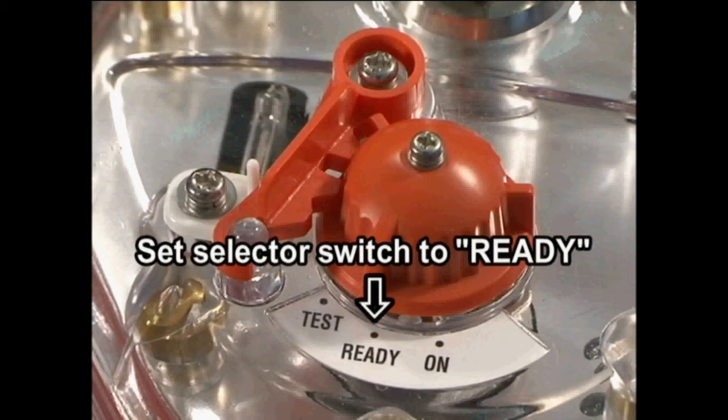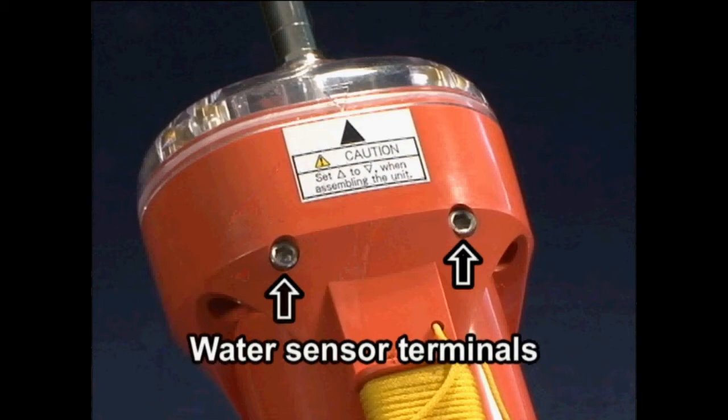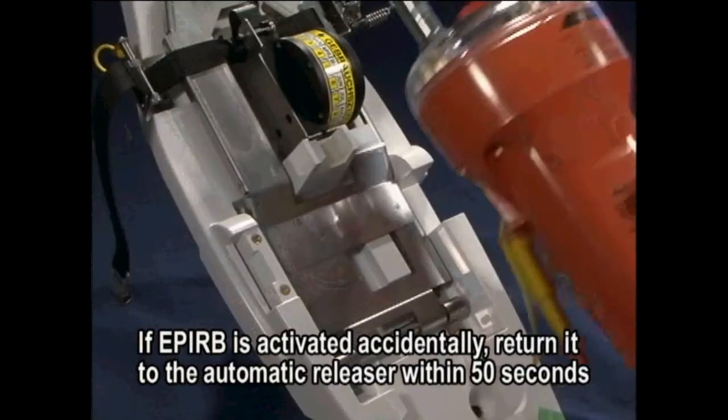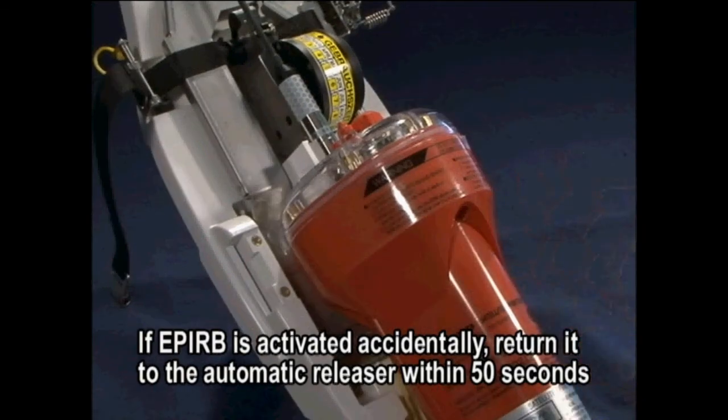When conducting maintenance, make sure that the selector switch on the main body is set to ready, and wipe the entire main body with a piece of soft cloth. Wipe each of the water sensor terminals separately. If the EPIRB is triggered by wiping of both water sensor terminals, you have 50 seconds in which to replace it in the automatic releasing unit before it begins transmitting a distress signal.